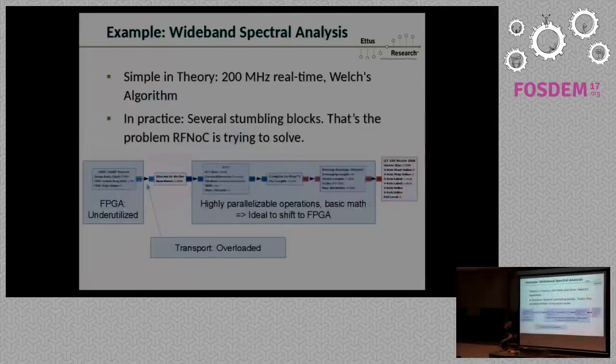So you generate data from your SDR, you stream it to the computer, then you calculate an FFT, 1024K, whatever, complex mag, moving average, and then you plot that. So very simple spectrum estimation application. This is sort of DSP 101 level. Already this won't work if you have a high bandwidth.